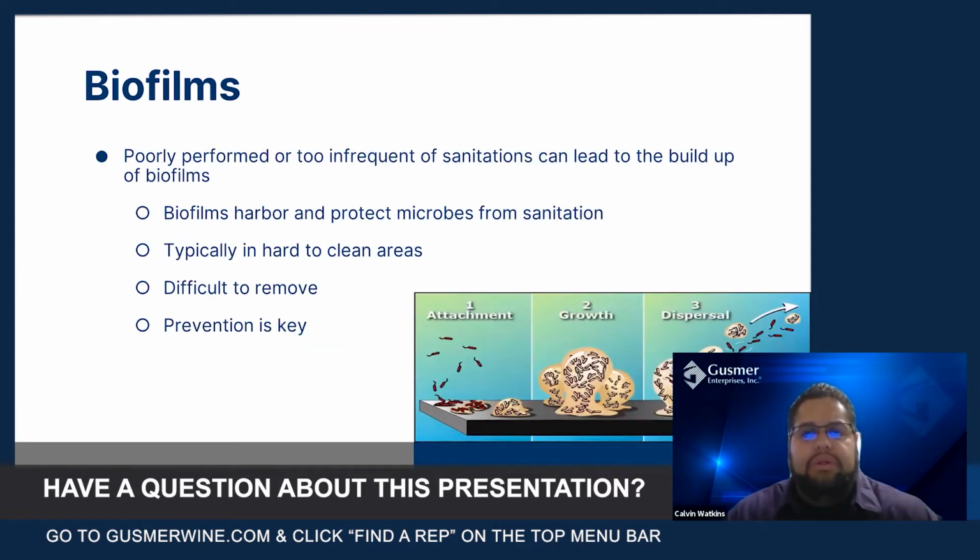I just wanted to really quickly touch on biofilms. A biofilm is essentially a film of organic material, may or may not have micro in it, but it's organic material that can adhere to the inside of your tank or your pipe. Over time, these biofilms can build up, and they're the cause of poorly performed or too infrequent sanitations. They're a house for micro, so micro will find a home there, multiply, and then be released from the biofilm.